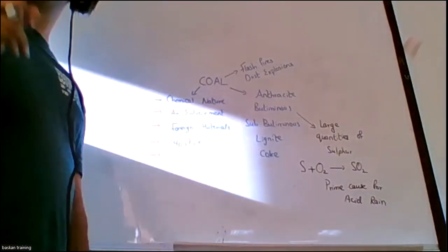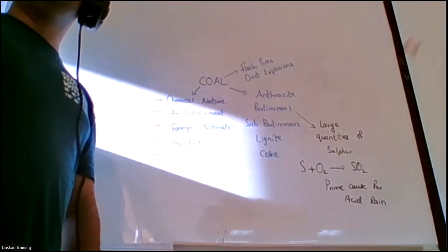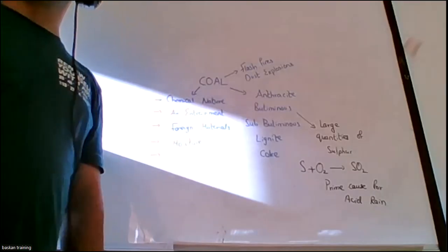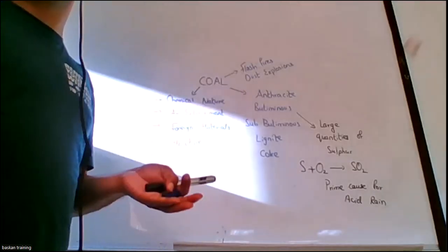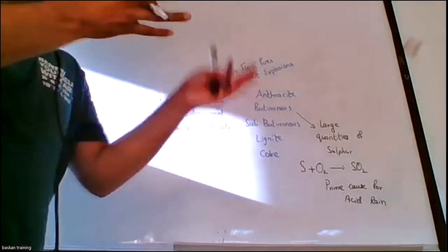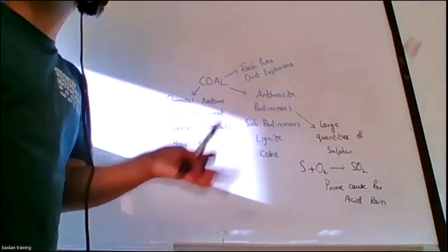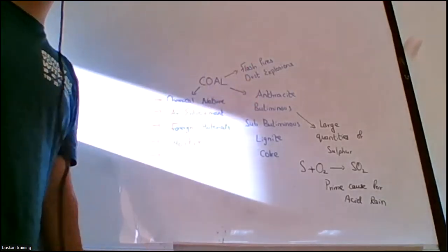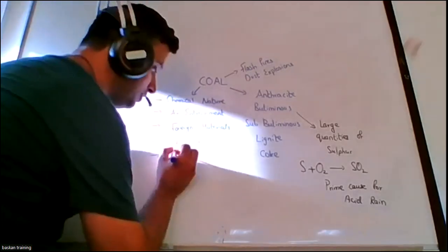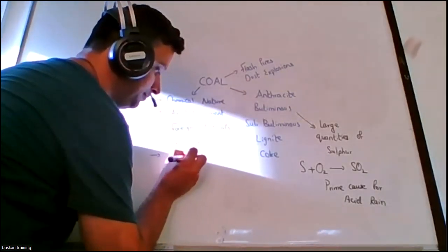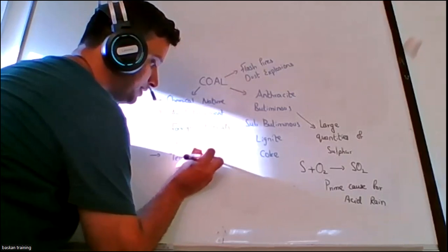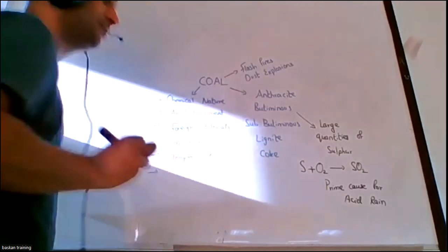Okay, then if there is any temperature rise because of steam lines, steam pipelines going near or beneath the coal storage pile, or because of the ambient temperature, if there is a temperature rise, it will affect the coal's heating process. The coal may start to heat up.